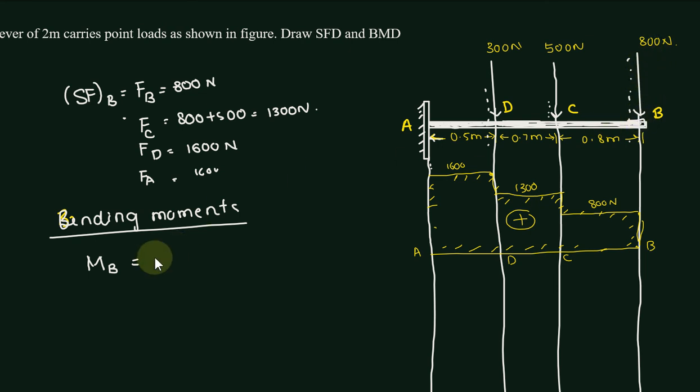So it is 0. And it is hogging, so all the loads are acting downwards and causing the beam to bend like this. As we are coming right to left, we are taking sections like that, so the beam will be bending like this, right? So here if you see, there is no load, so simply this is 0. Here bending moment at C. So if we see, we have 2 point loads and only one distance we have to consider. For example, this is the load.